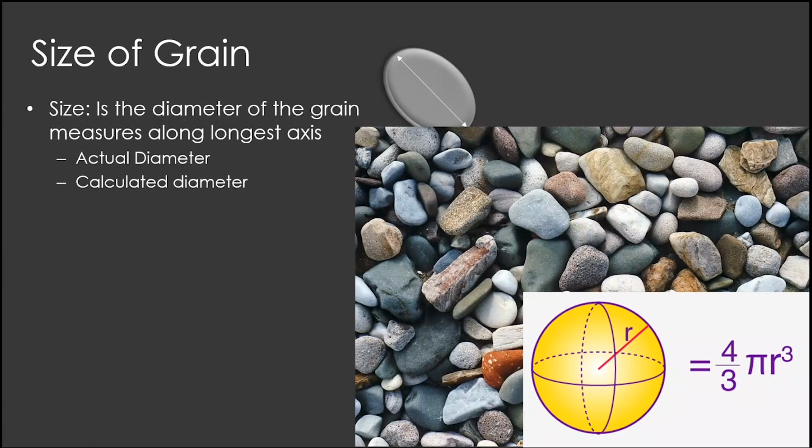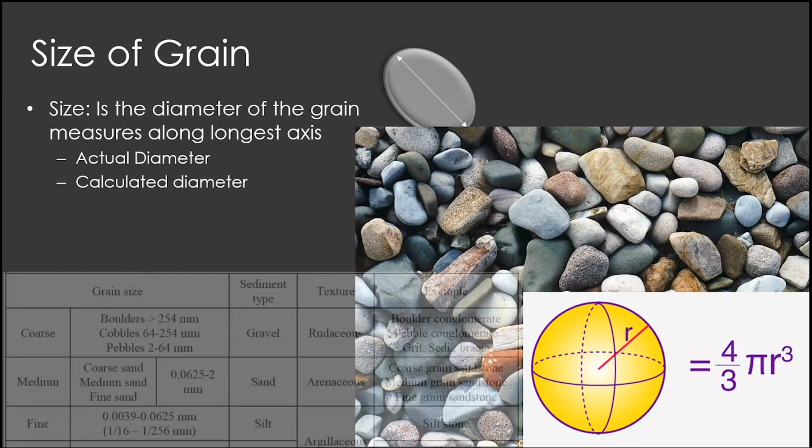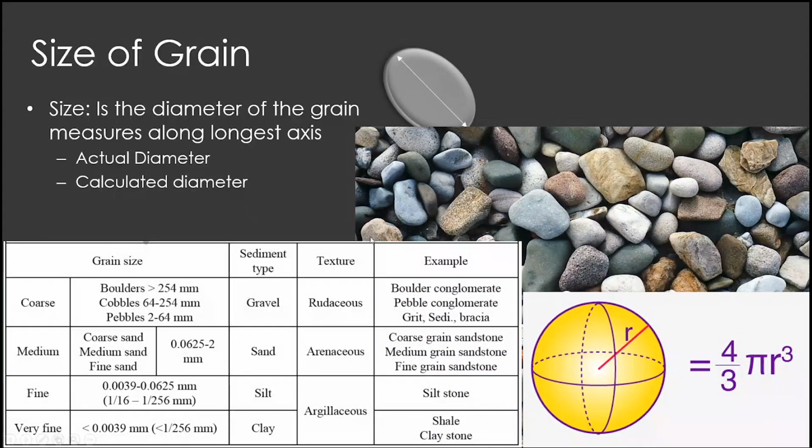The sieve method is that we take different sieves having different sizes of openings, and we put the grains into the largest sieve. Then they pass through different sieves which have reduced sizes of openings, and when you sieve in a sequence, we get gradations: the coarser sediments on the topmost sieve, then the finer sediment, then the next, so that way we can find out the size of the grain. There also we assume that the sediments pass through a particular size, so that diameter we take as the diameter of that particular grain. Based on these characteristics, we classify the sediments into different categories.